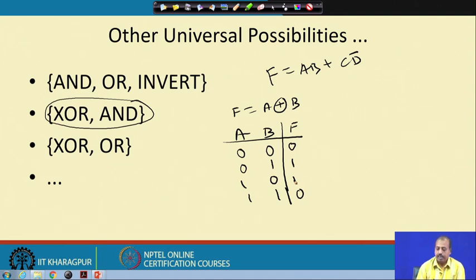Now, you see that if I make this B input forcefully equal to 1, the B equal to 0 combinations do not come. So, B is made forcefully equal to 1. Then if you give A equal to 0, you get a 1 at the output. If you give 1 as an input, you get a 0 as the output.